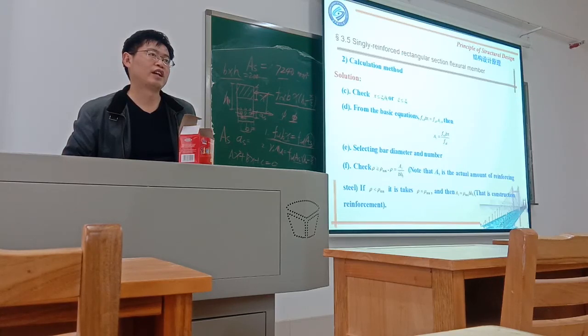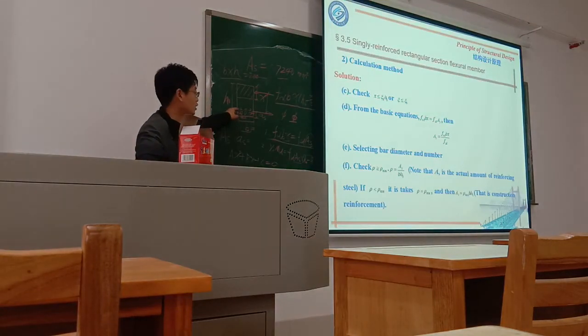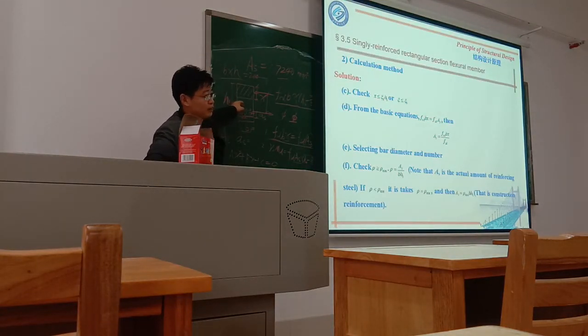So your design has some problem. For the large diameter, you just chose 5; for the 25, you use 7. Normally the first layer cannot have a smaller number than the second layer; the upper layer normally is not larger than the lower layer in number.